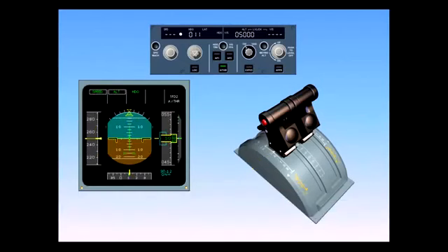When the aircraft reaches the target altitude, the autopilot flight director goes into the altitude mode, and the autothrottle switches to the speed mode as indicated on the FMA. In this mode, the autothrottle continuously adjusts the thrust to maintain the target speed.